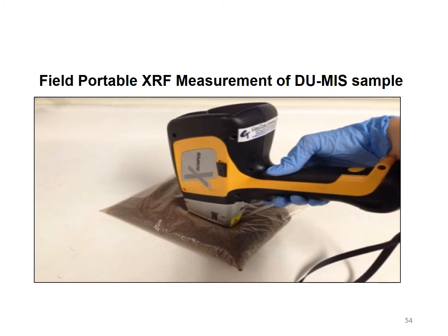You typically take these through a plastic bag anyway, and instead of just one discrete sample you might do if you were doing this in the field, then for this multi-increment sample you've collected to represent the surface layer in your chosen DU, you can sample this a great number of times in the bag and average them to get what we think is a better representation of what might be in that decision unit.